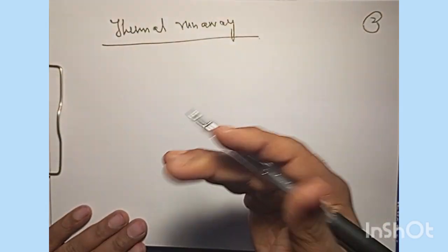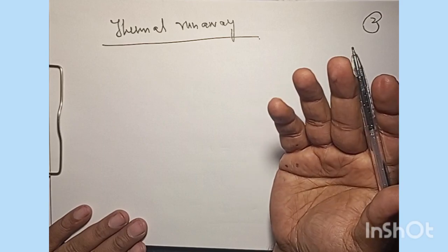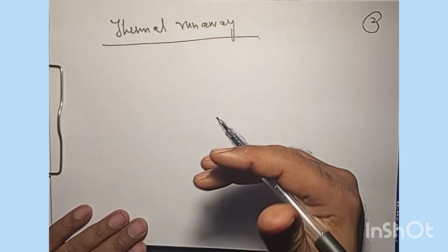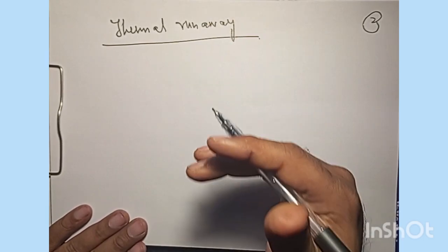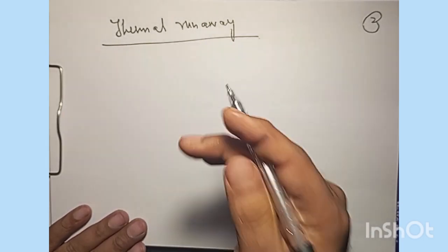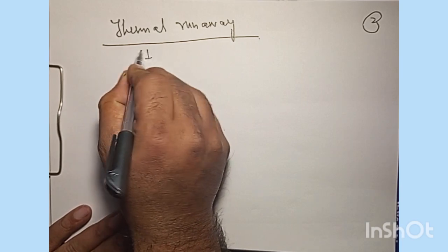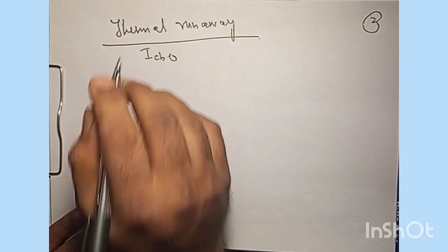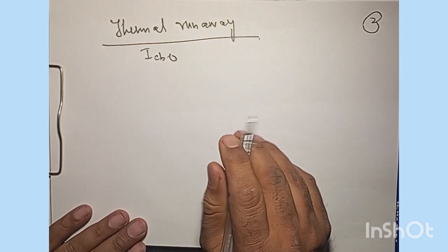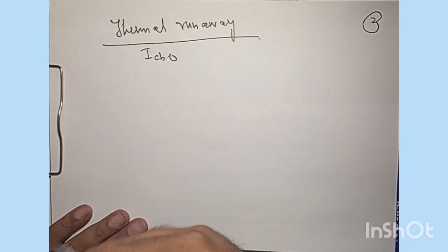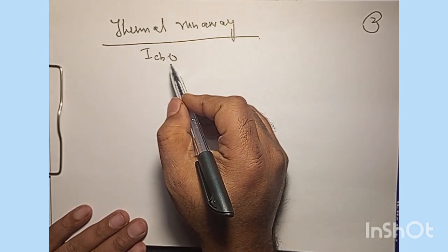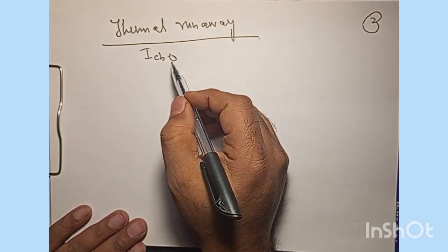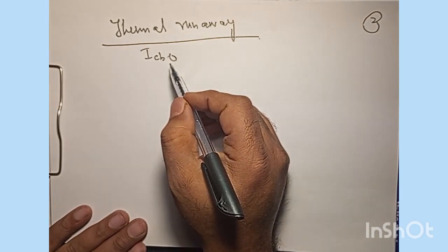It produces heat within the transistor, and this raises the transistor temperature, and thus the collector leakage current, ICBO, increases in magnitude, and this certainly increases the collector current.